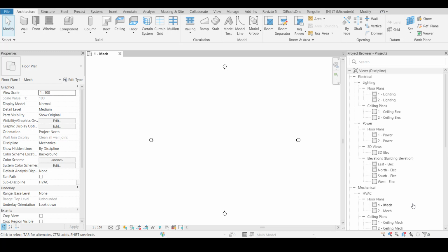So if you are working for a consultant, in that case you have to submit the complete set of your drawings from BIM for the acceptance of the client, and that we call the IFC package. That's when you give the complete information of design to the next party, meaning your client, and then he can distribute the same design to the subcontractors or contractors to get the work done at the site. Now that is the case of the designers. When I say designers, it means the consultants, whether architectural, structural, or MEP, whoever.